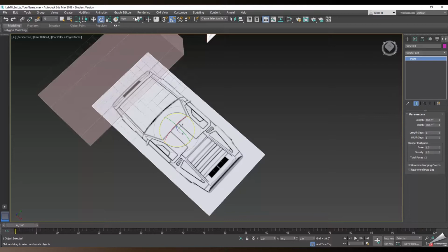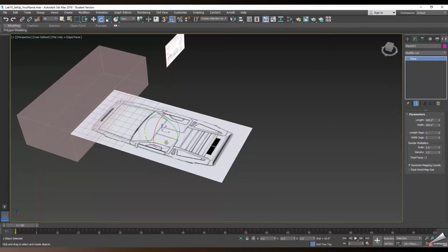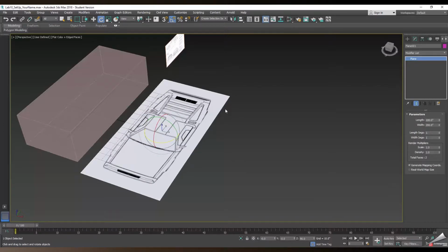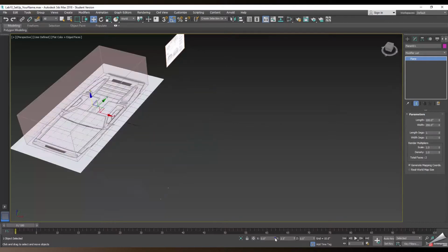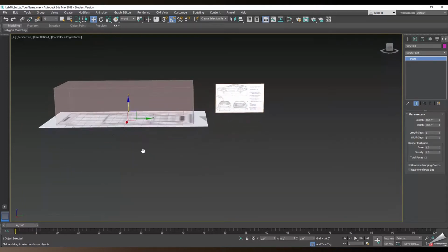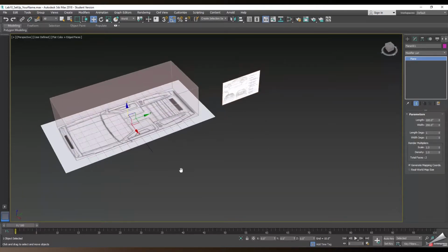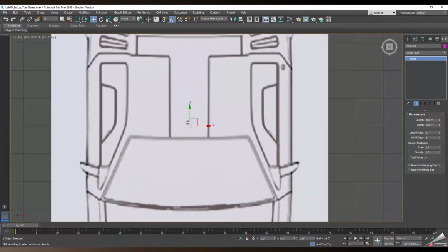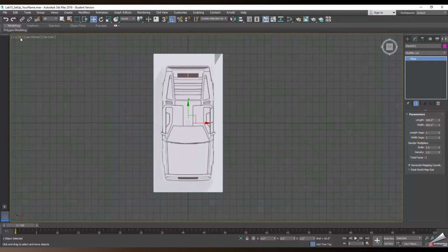Let's grab the rotate. Make sure your angle snaps toggle here is turned on up top. Make sure it's blue. And rotate it 90 degrees. There we are. Grab your move tool or hit the W key. And since we're in the world coordinate system, I can down below here zero everything out. 0, 0, 0. And there we are. Look at it from the top. I'm going to hit T for top orthographic view. It switched right over here automatically from perspective to orthographic view.